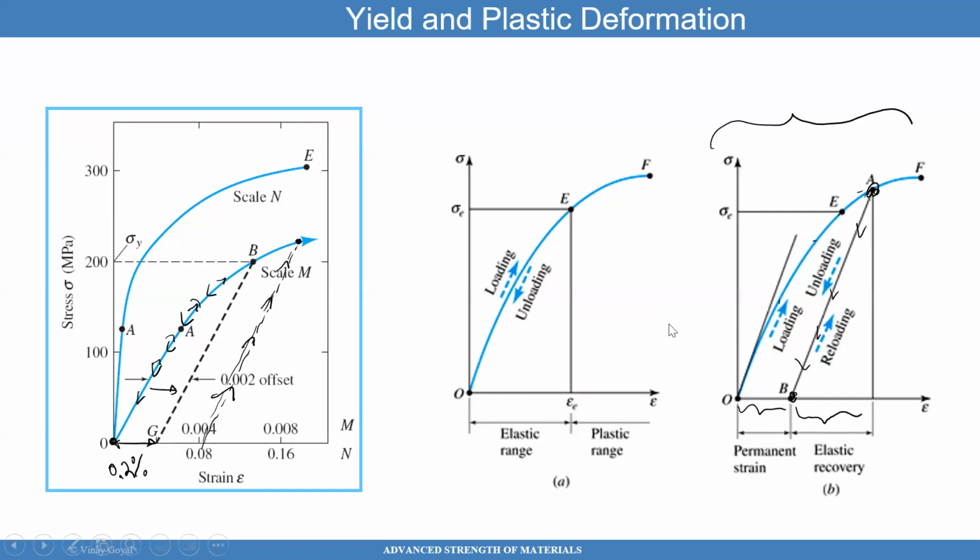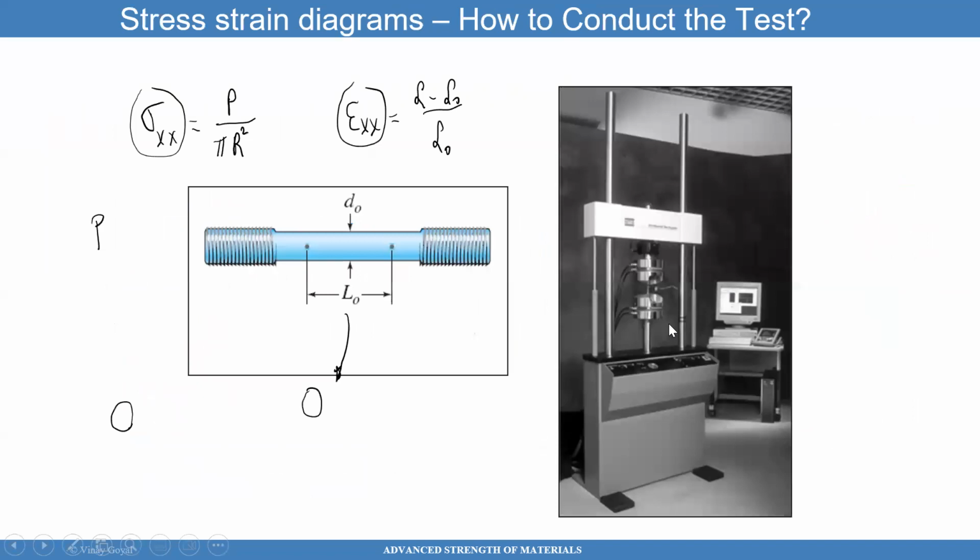So what I've shown so far is how you deal with taking the stress state and dividing it by the original cross-sectional area, and the strain is also divided by the initial length. So when you construct a curve like that, we call that the engineering stress strain curve.